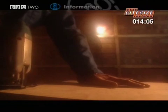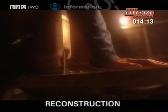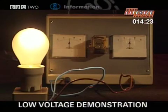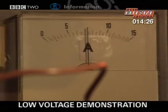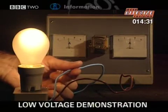What does protect you is a residual current device, or RCD. Receiving an electric shock will still hurt, but the risk of electrocution is much less. All circuits have 2 connecting wires. The current flowing in each wire should always be the same. If you accidentally touch a bare wire, the leakage is immediately detected by the RCD, causing a switch to trip.